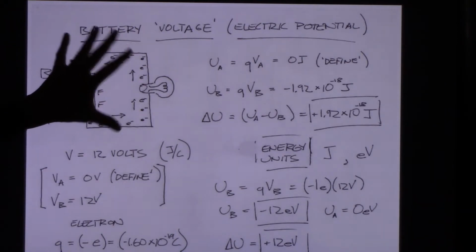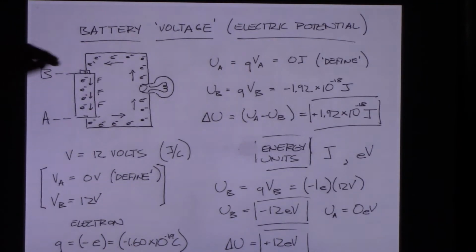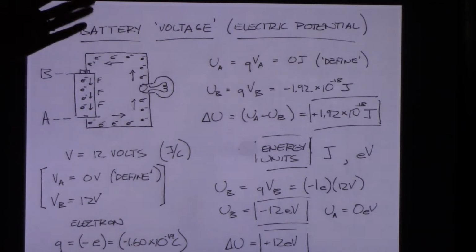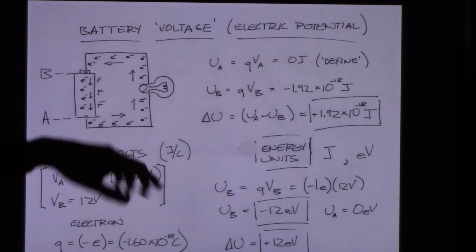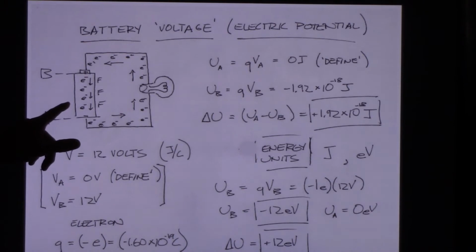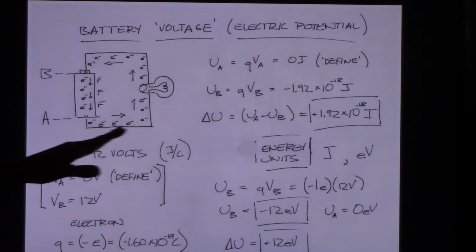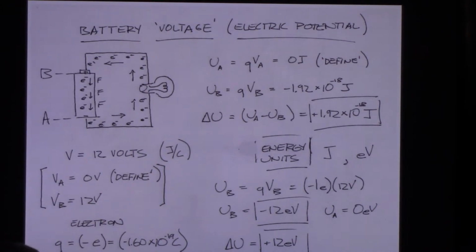So I've already got electrons here. I have electrons over here in this light bulb, in that filament. As soon as I close the switch, which I should have put a switch in here, those electrons are going to start moving through that light bulb, and the light bulb lights up. So again, I don't have to wait until electrons from the battery reach the light bulb, because there's already a bunch of electrons waiting. They're already just milling around in the circuit, waiting for somebody to close that switch. And then immediately they start moving at all locations.